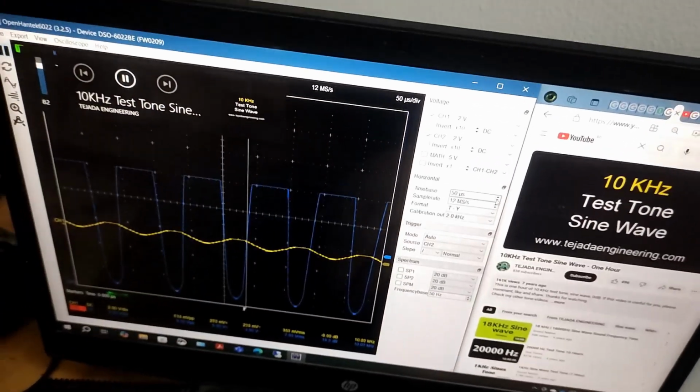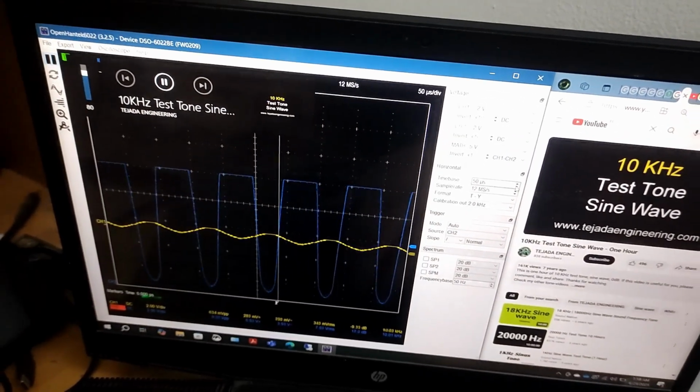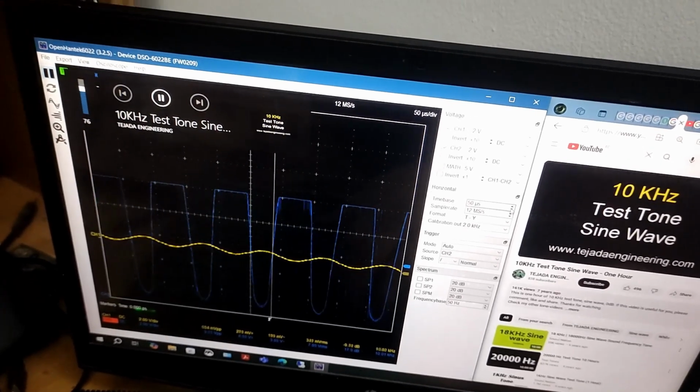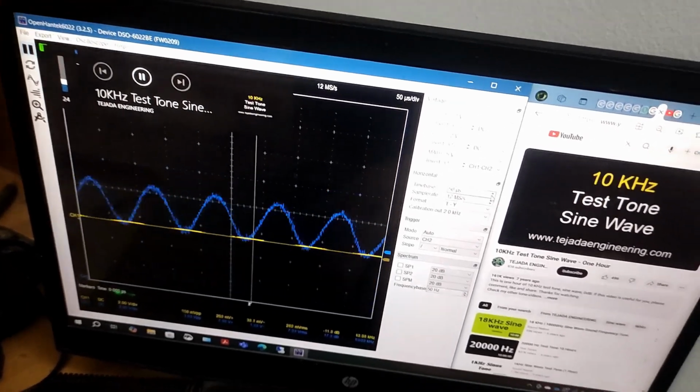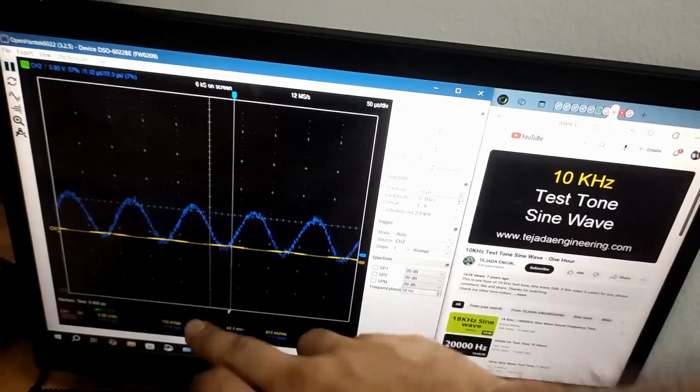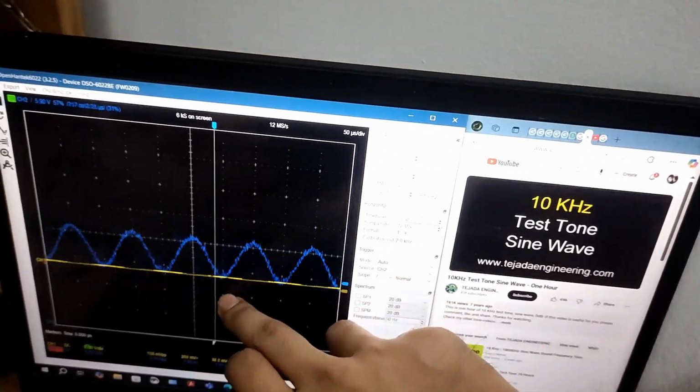We can reduce the effect of cutoff by reducing the input sinusoidal voltage amplitude. Let us see what happens. If we reduce it enough, we can see that we retain the sinusoidal output waveform.